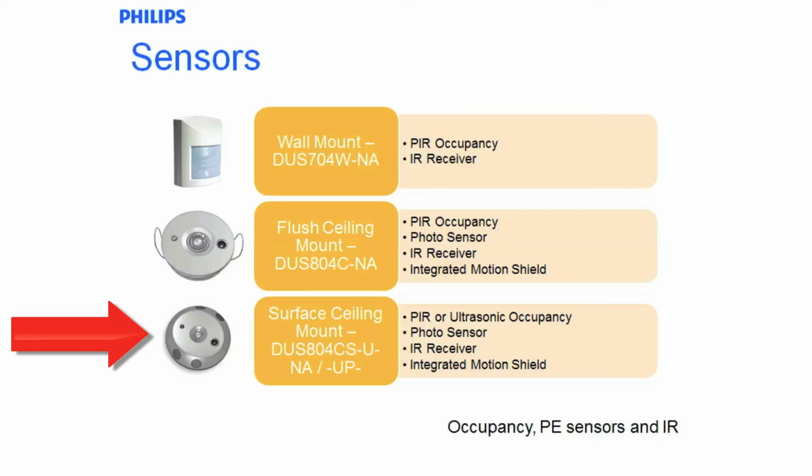as the ultrasonic component. The way these sensors should be set up for commissioning is to use the passive infrared for the initial sense of motion. Then once you have sensed motion, you engage the ultrasonic to then look for fine motion. It's important to note that when you are utilising ultrasonic sensors, you can't have more than one in a single space because it will cross-interfere with each other. Effectively, one will trigger off the other.